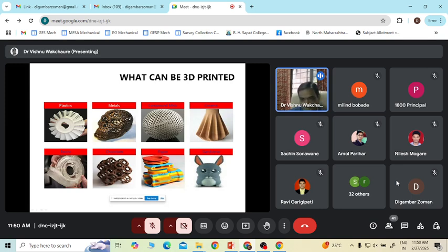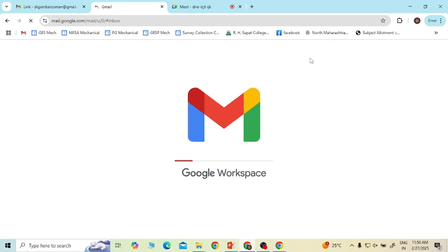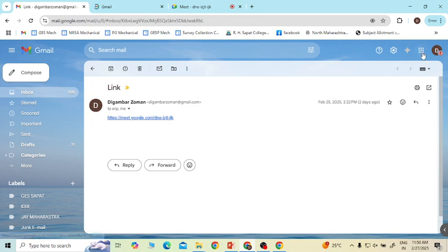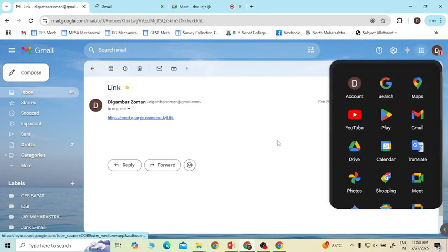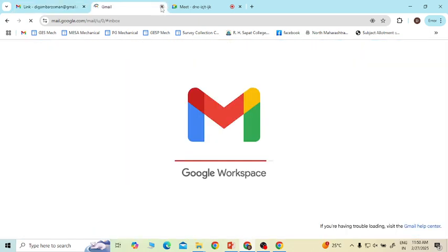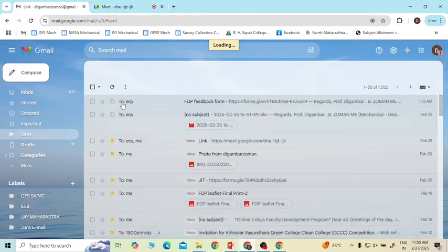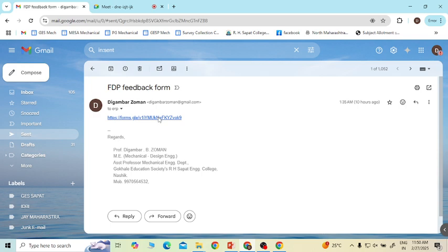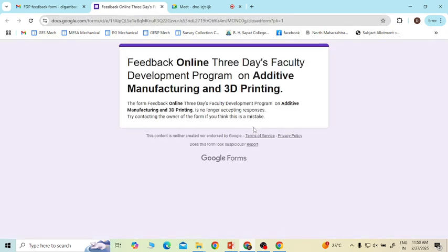And sand, which is a part of ceramics, can also be printed. The printing techniques will be different, but you name the material and we can have it. If you look at metals, from simple materials like aluminium to titanium, that range of materials can also be printed. Metal printers of that type are available. Why I said titanium is that it is very hard to machine, and very high temperature is required for fusing that powder.